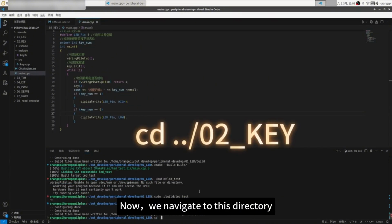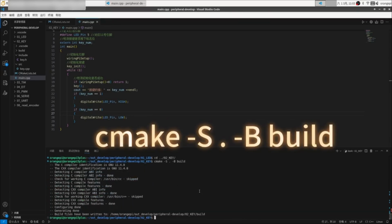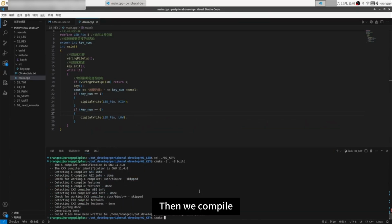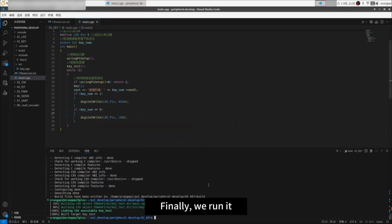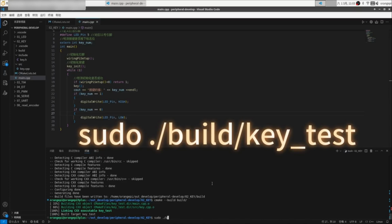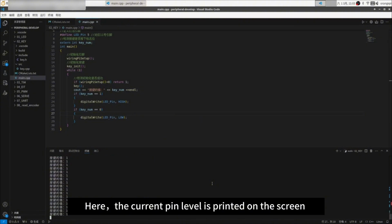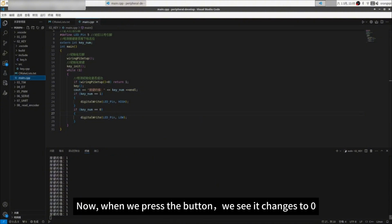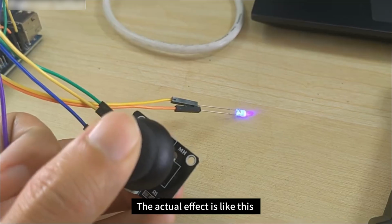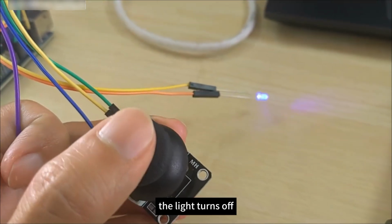Now, we navigate to this directory. Similarly, we first create a build directory. Then we compile. Finally, we run it. Here, the current pin level is printed on the screen. We can see it's 1, high level. Now, when we press the button, we see it changes to 0. The actual effect is like this. When we press the button, the light turns off.